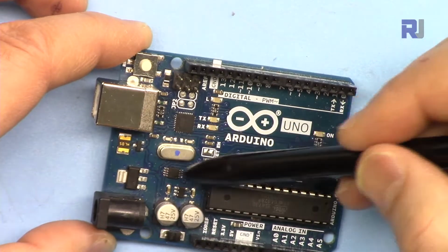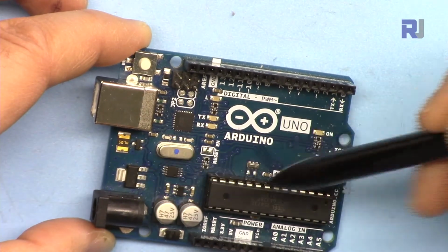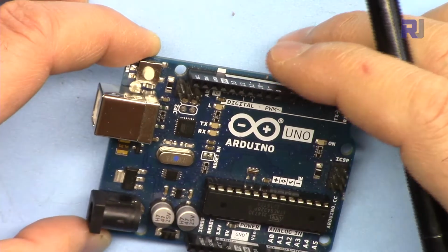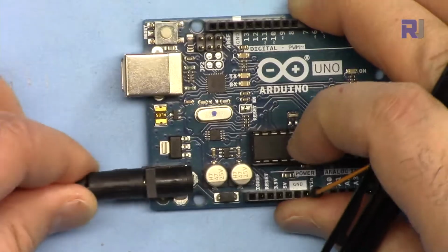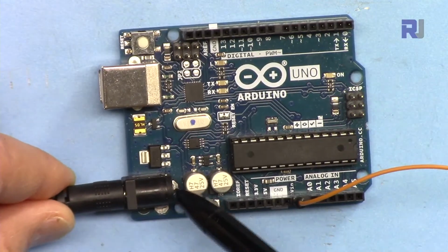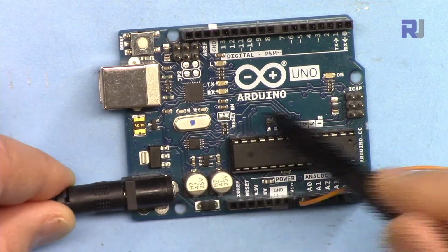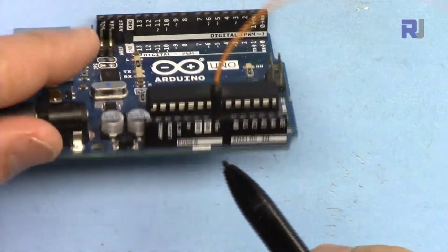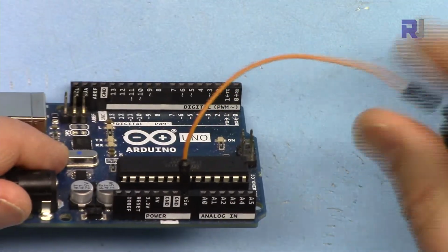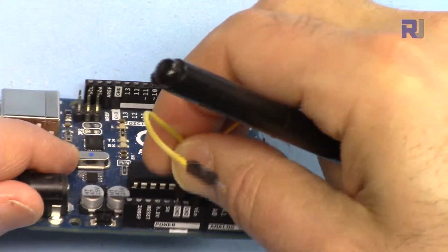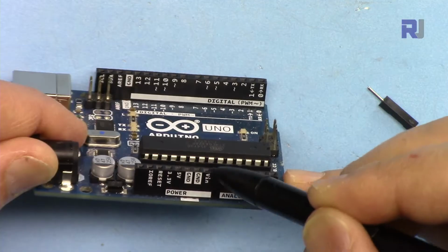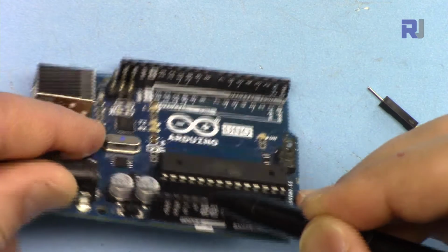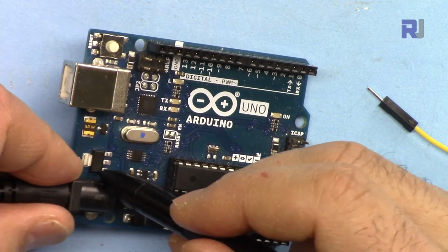The voltage comes here. It is being converted to 5 volts for this chip and for the USB as well. Power it up with a power adapter from here, up to 25 volts will go here, and this is 5 volts supplies for all the circuit. Or you can power it up from this pin VIN. You can connect external power from here and the ground. You can connect up to 25 volts, one pin here, the other one to the ground, and it will go here to convert it to 5 volts.